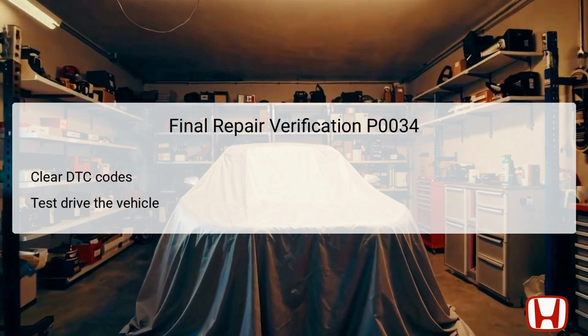Once the necessary repairs or component replacements have been made, the final step involves verifying the effectiveness of the repairs conducted for DTC P0034. Begin this process by accessing the Honda Diagnostic System, HDS, and clearing all diagnostic trouble codes stored in the PCM. Following this action, it is imperative to take the vehicle for a test drive to evaluate if the initial symptoms and DTC P0034 reappear.